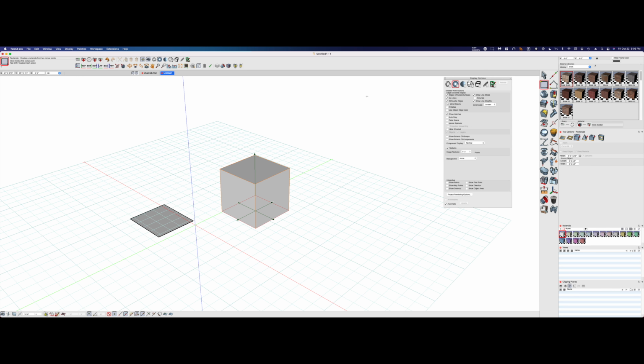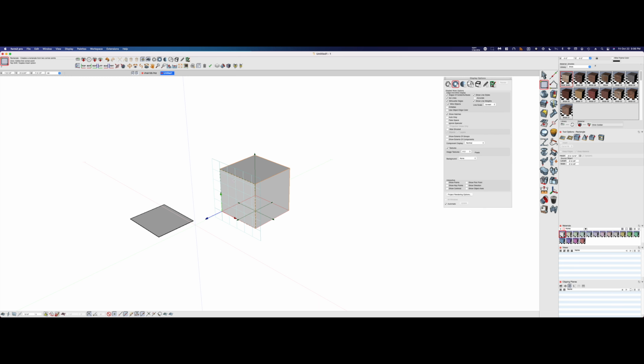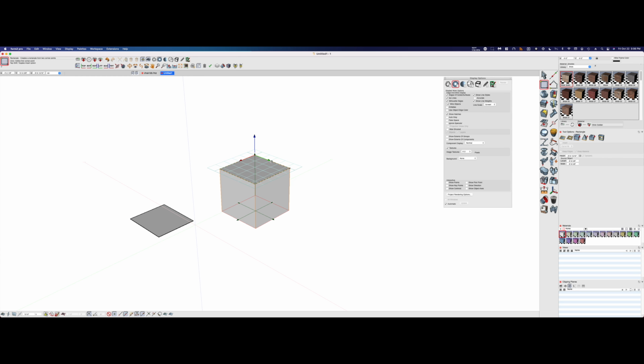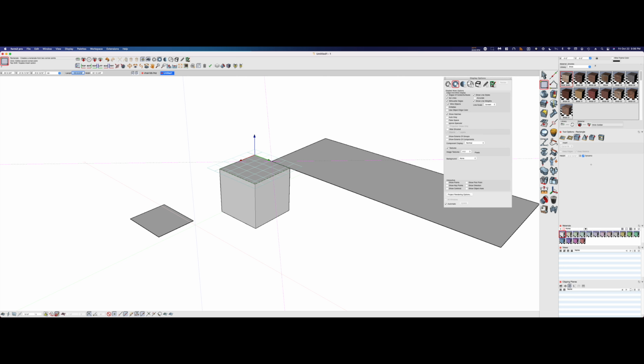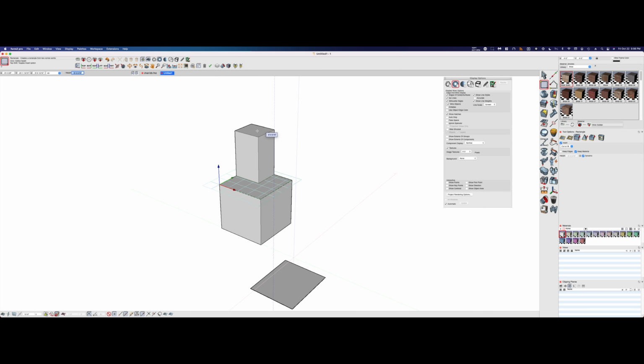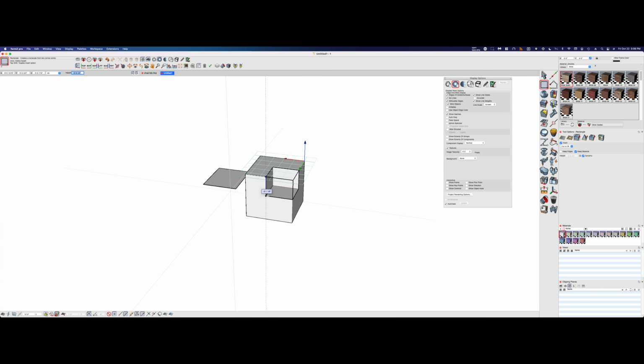One of the features is that you can draw on objects, kind of like SketchUp. When I draw on something, if I use the insert option, I could do one of two things. I'm on this surface, I could create more surface, or I can subtract.